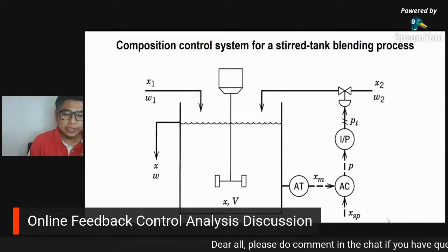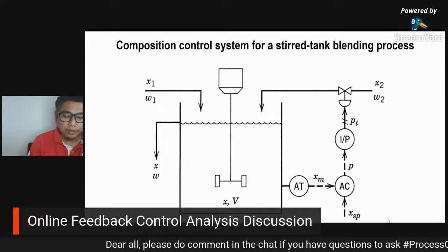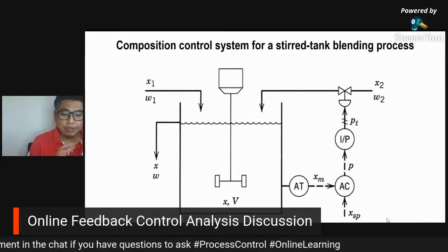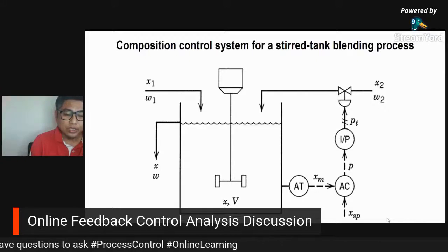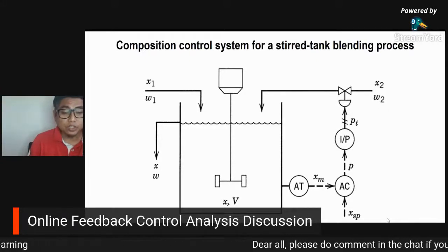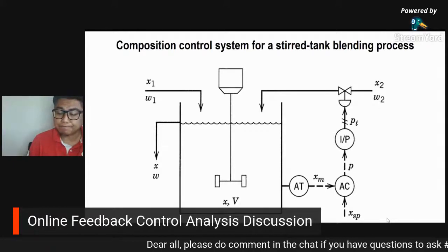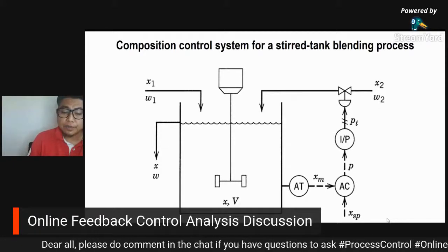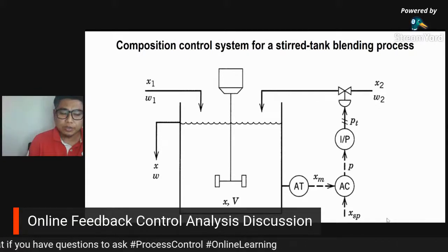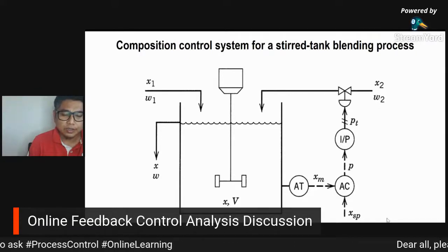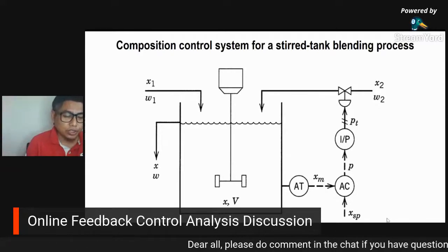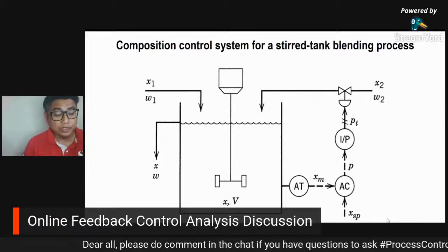So this is a constant level system, since we have the effluent discharged at a certain level, at a certain height. So there is no need for us to control the level here. From what we covered in our previous classes, once we are given this kind of simple process flow diagram with certain instrumentation, we cannot call this a P&ID because this is very simple.